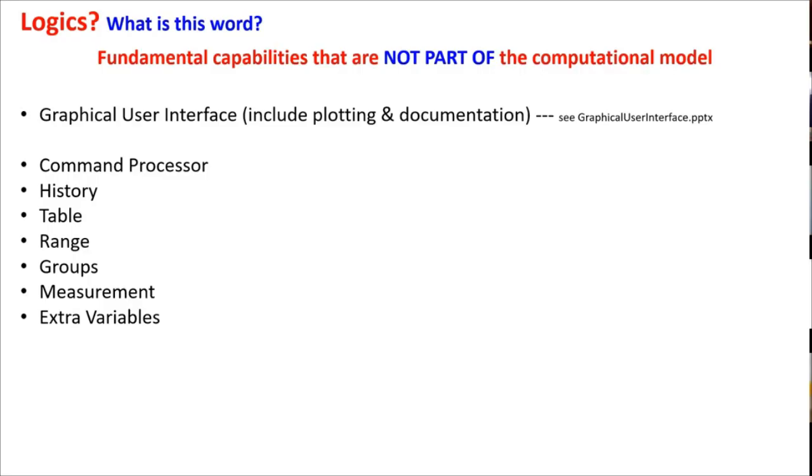And then there's these things called extra variables. And the idea is very powerful and very simple, is that every object in PFC, like a ball, you can associate a FISH variable with each one. And a FISH variable, as you'll find out, is a general thing. It can be a vector, it can be a scalar, it can be a string that says, my name is Fred. And so every single ball, you can just make up your own FISH variable and store it there.